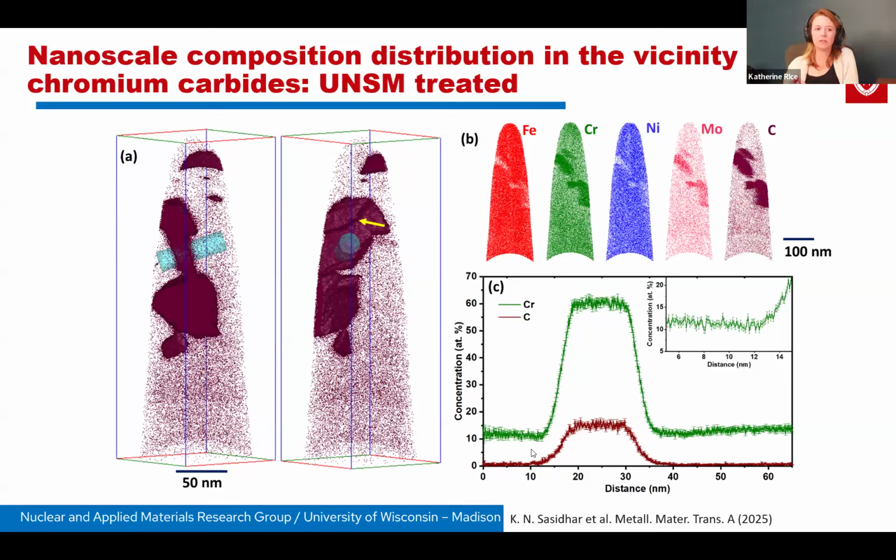Okay, great. Do you think that this process could be applied to different geometries, like a circular pipe, something like that? Because as I understand, those weld seams are really a big failure point. Not a lab scale setup, but you can definitely engineer a setup at the industry scale to work with curved geometries. There is work being done at institutes in the US that we are aware of on curved surfaces. These peening technologies have been applied to curved surfaces, so that's very well possible.